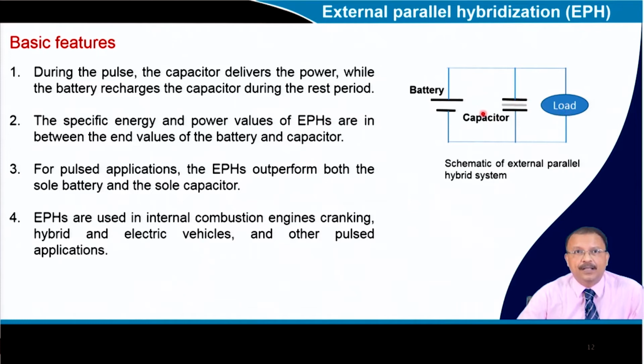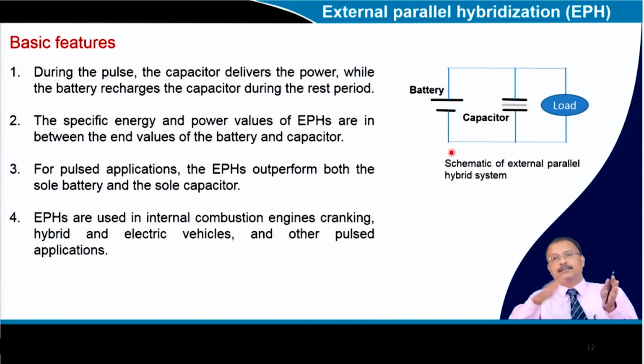So, when there is a pulse, then the capacitor drives the power, and the battery recharges the capacitor when the battery is kept idle. So, the specific energy and power values of external parallel hybrids are in between the end values of the respective battery and capacitor.